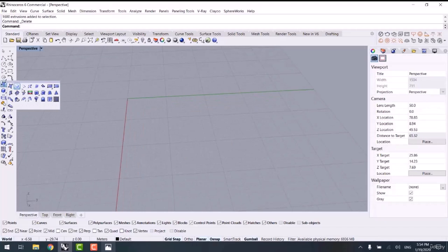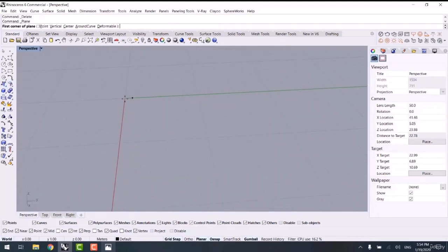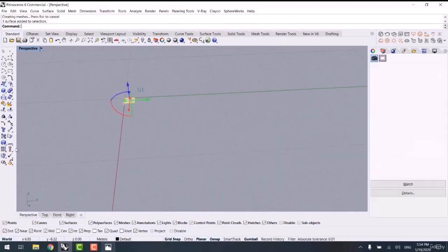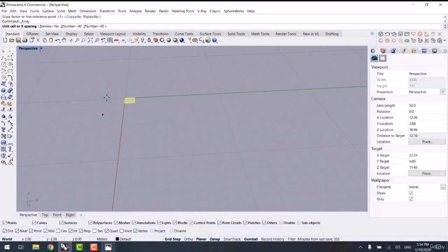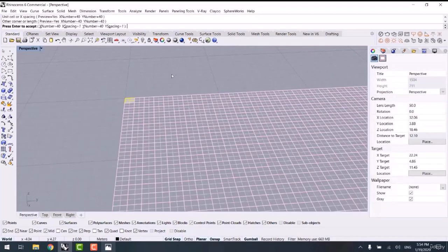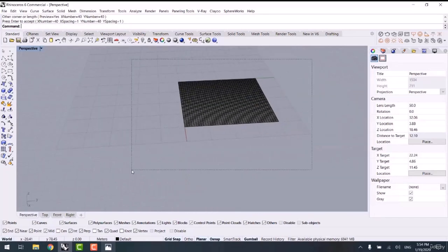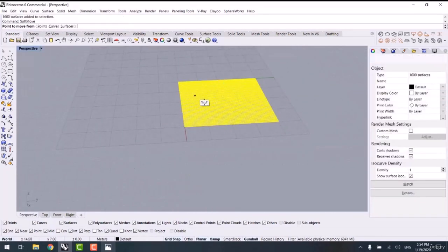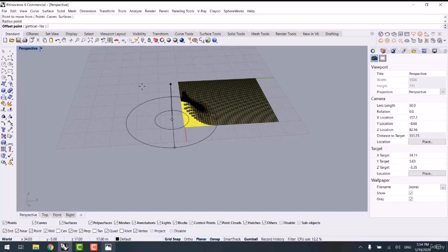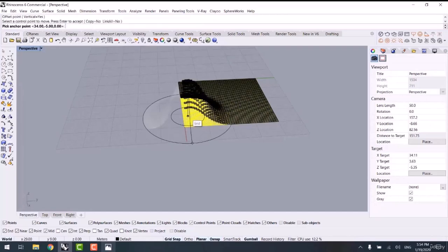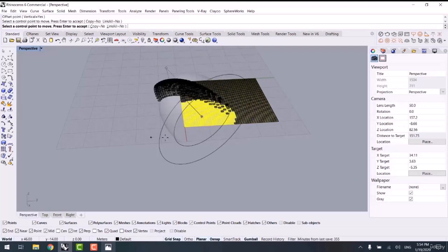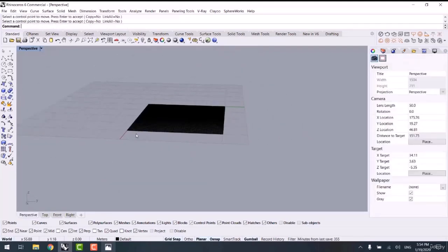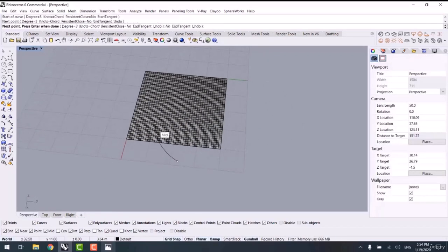And at the next case, I want to draw some planar surfaces and then array them in the construction plane. Here I select it and then I array it at the same numbers, 40 in each direction. Then we select these to soft move. Following that, the point to move, radius, offset point, and fall off point. Watch this. You can move them smoothly and edit the dense points. All that works on all of the objects.